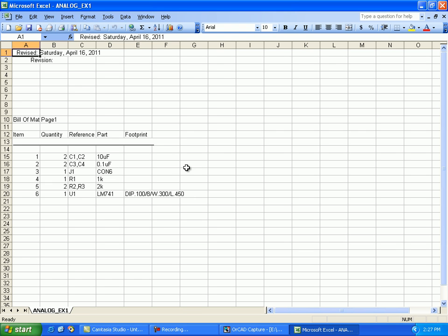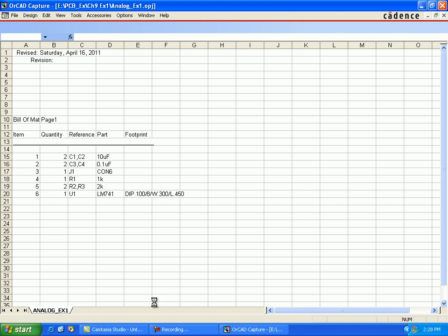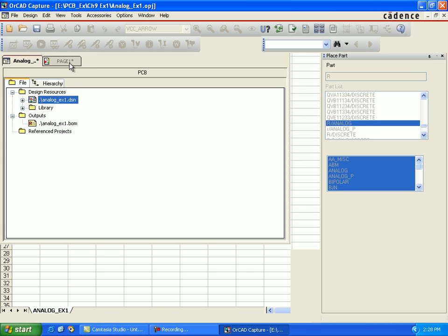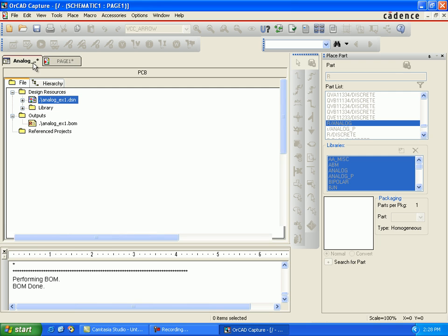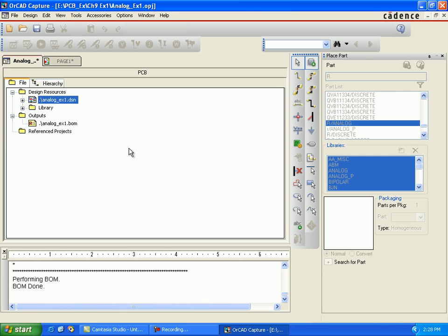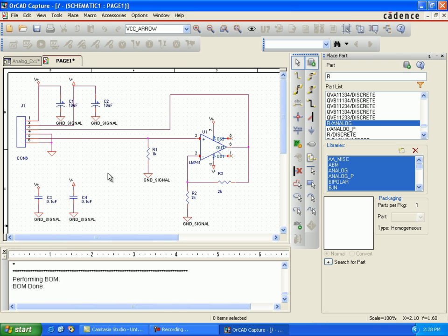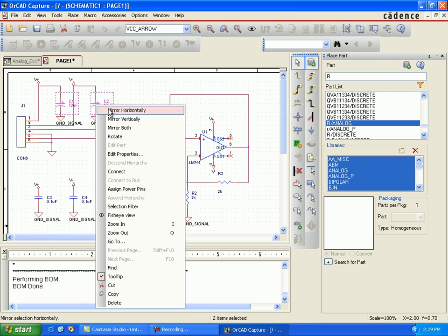This will generate the bill of material, what components we are using and the list of components in the Excel sheet. So this is the item quantity we want, capacitance, and now we want footprints. Footprint is the component dimensions we are going to use for our project, so we have to specify whether it is surface mount, crystal, capacitance, whatever it is.